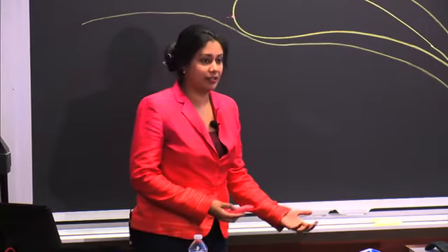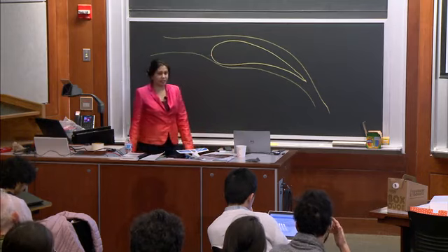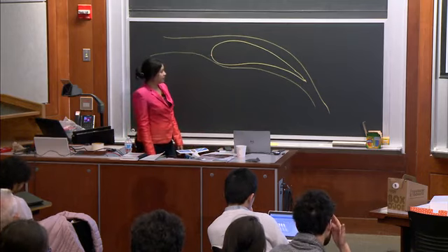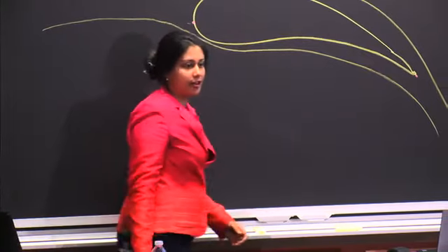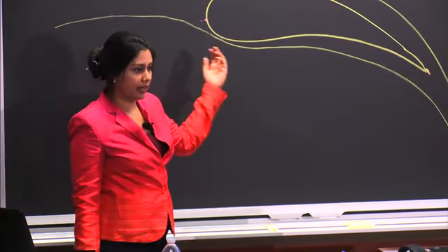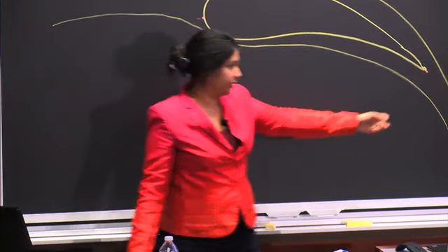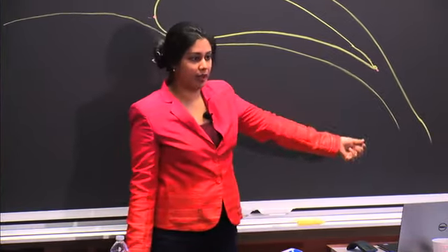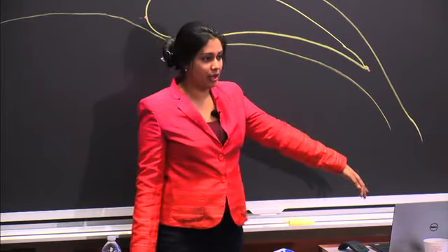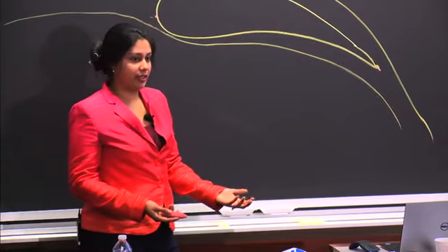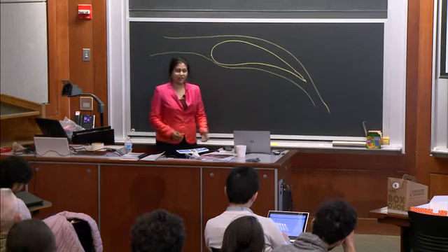But in this false theory, equal transit theory, they say that you have to reach the end at the same time. They also say that there is more distance basically to cover because of the shape of the airfoil. So in order for the molecules going over the top to arrive at the same time as the molecules over the bottom, they have to go faster. And so since the air is moving faster over the top than the bottom, that's what creates lift. So that's false, and there are many reasons why it's false.